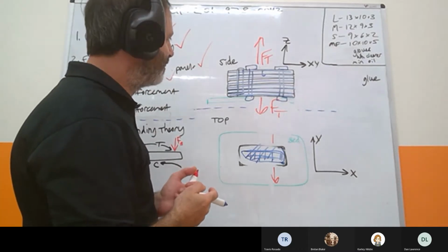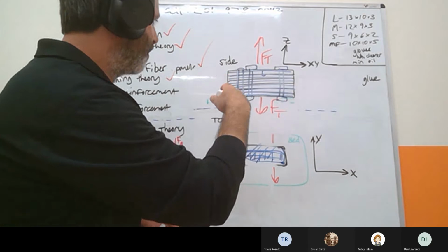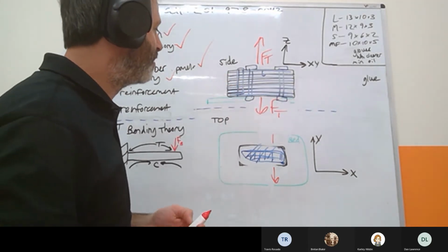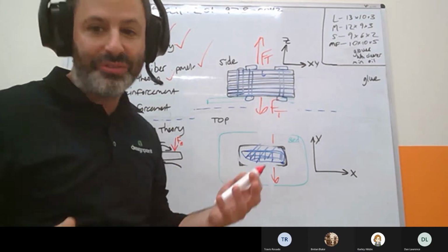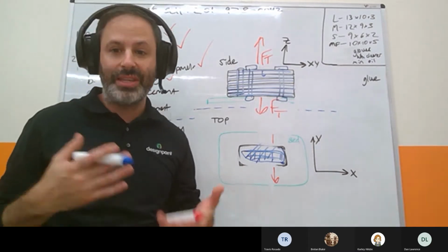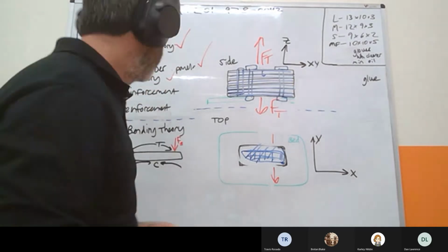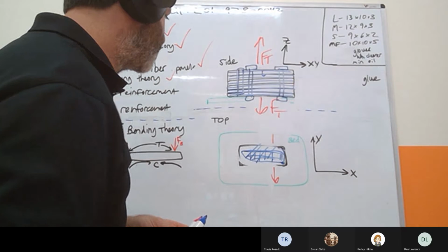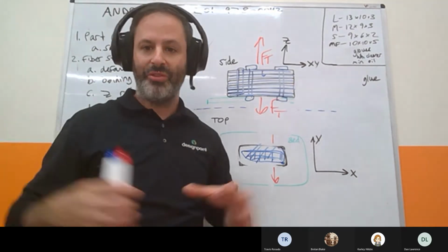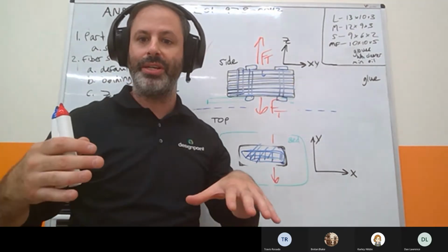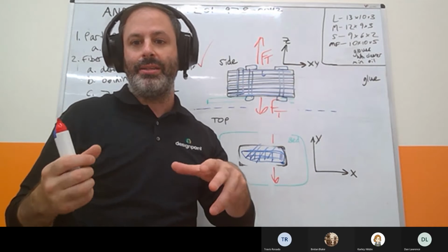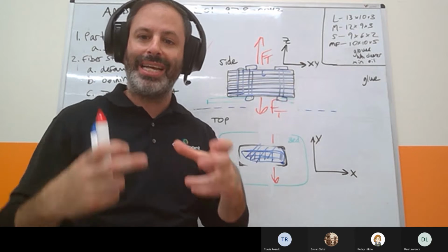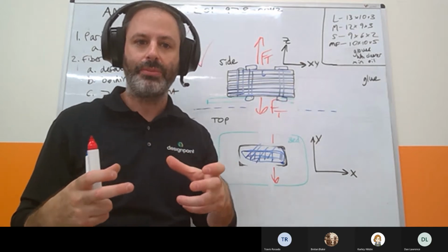We talked about the different loading conditions for fiber reinforcement. We talked about the different loading conditions without fiber, which you can see is all very similar. And we talked about the different types of fibers for reinforcement, right? Perimeter fiber, more for an XY load, because in the XY, you want to align as much of your fiber in tension as possible.